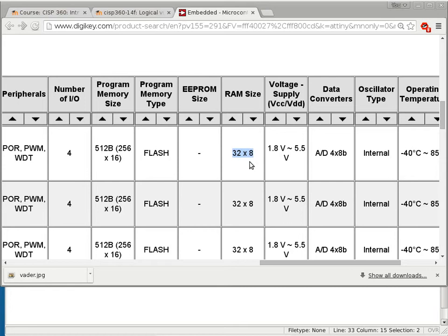In the past, when toasters break, they tend to char or burn your toast, because the temperature control is just a mechanical thing. When it heats up, the bimetal thing just bends, and it will automatically disengage the current. And you can have some toastiness control, but it's usually kind of vague, and it varies from one toaster to the next.